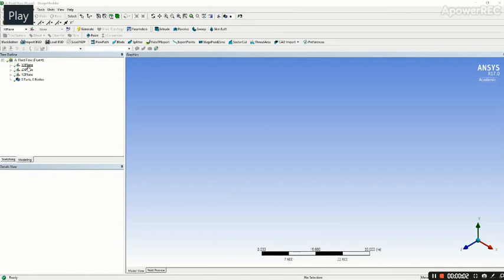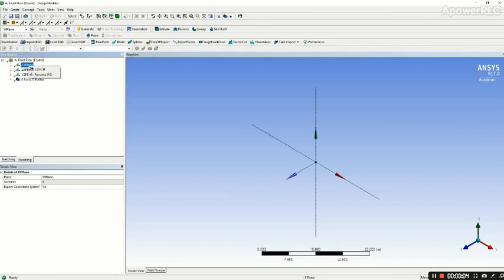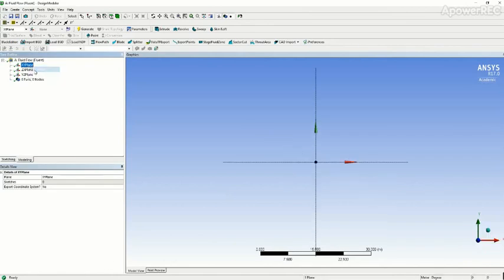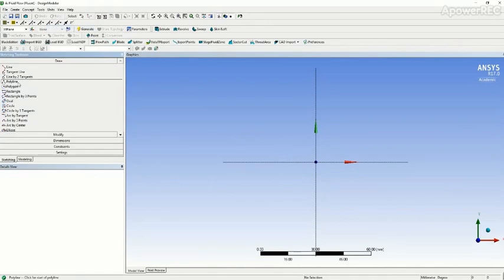Hi. So we are already in the geometry plot in the CFD Fluent file. What we need to do is first make the converging diverging nozzle. For that, first we are changing the units to millimeters, and we use a polyline feature to draw a rough sketch of the converging diverging nozzle, and that's what is being shown in the video right now.